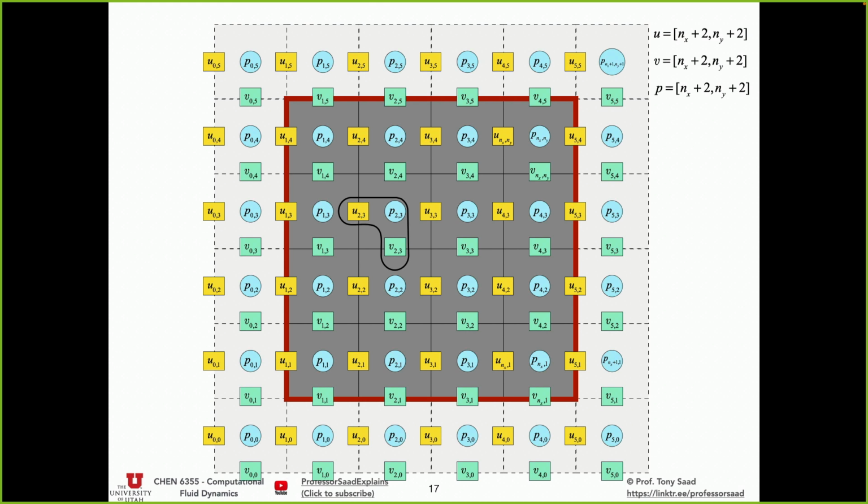You can count them the same way I counted the u velocity. So when you spend a minute and think about this grid, you're like, yeah, you know what? It's not that bad. My reference point is always going to be the p pressure. But then I have to think, when I'm implementing the u velocity component for the u momentum, that this is my control volume.